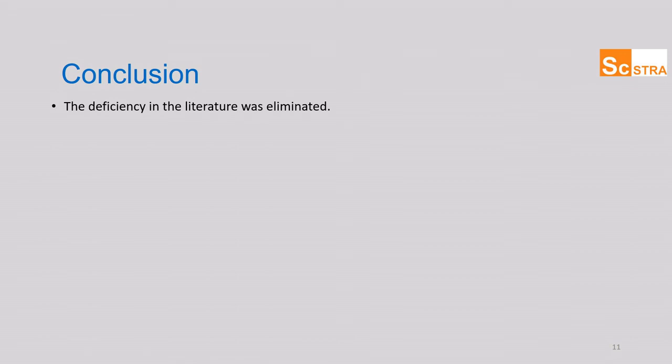In this paper, local ground movements were examined as a result of the broken and unbroken wave effects around the head section of a rubble mound breakwater in an experimental manner. The experiments were carried out with a specific rubble mound surface slope, 2 different sandy bed materials, and 5 different wave periods.